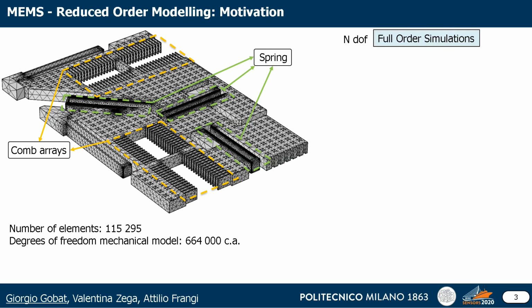A finite element model may involve capital N degrees of freedom, with capital N ranging from a few hundreds to millions of degrees of freedom. In the device considered, a structural mechanics finite element model referred to 1/4 of the whole structure has 664,000 degrees of freedom. In addition to this, multiphysics and nonlinear phenomena increase exponentially the computational effort.